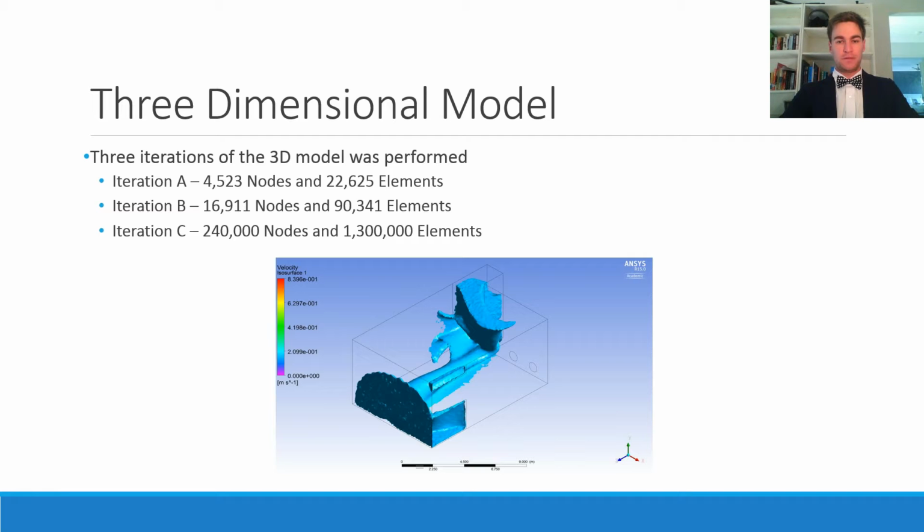The image is of the isosurface plot for velocities of 0.15 meters per second and greater. Therefore, the results from iteration C suggest that much of the anoxic zone is below the recommended velocity. Furthermore, the three-dimensional model highlights the limitations of two-dimensional modelling, in that the vertical clearance between features cannot be considered. For this project, the vertical clearance between the top inlet and the A-recycle pump results in a different flow pattern to that observed from the two-dimensional model.